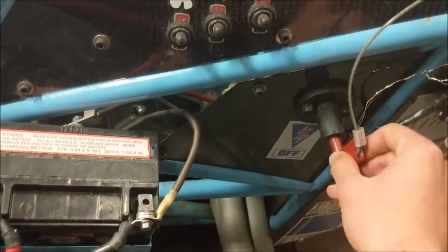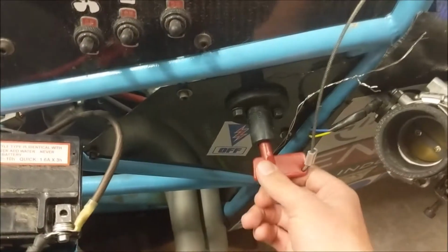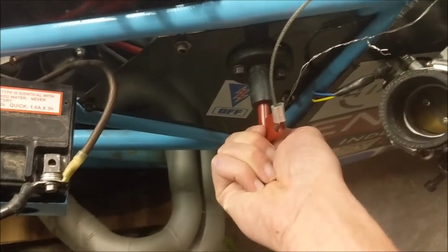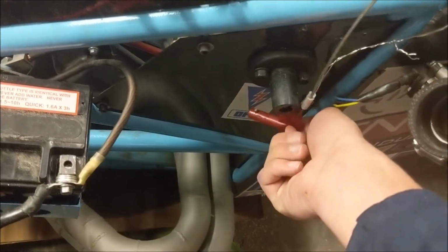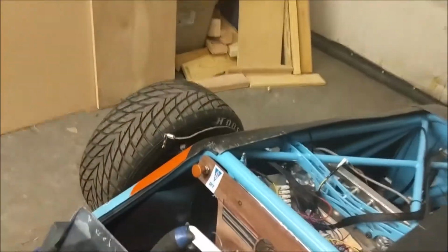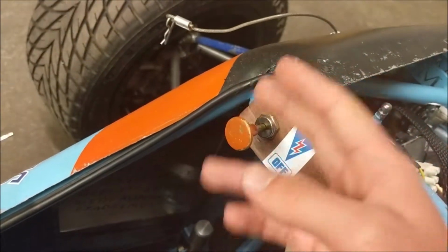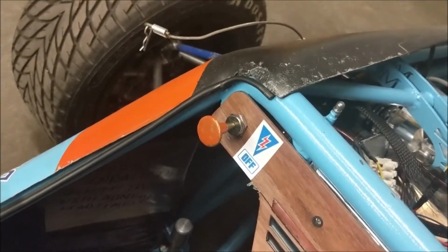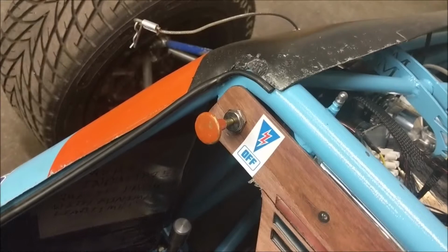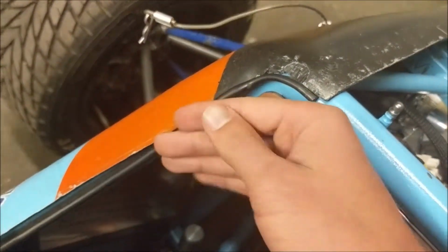A very important safety feature on the car is this switch. This switch is keyed. Once it's turned, the car is on. Notice if you take it out, the car is off in the off position, but if you press it in, the car turns back on. So make sure this keyed switch is taken out of its position and left to hang. Furthermore, this switch lets the car be fully controlled. If this switch is on and that switch is on also, then the car can start and fully function. When working on the car, be sure both switches are turned to the off position.